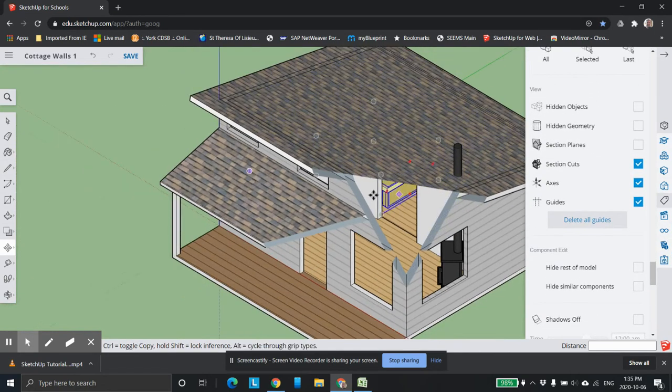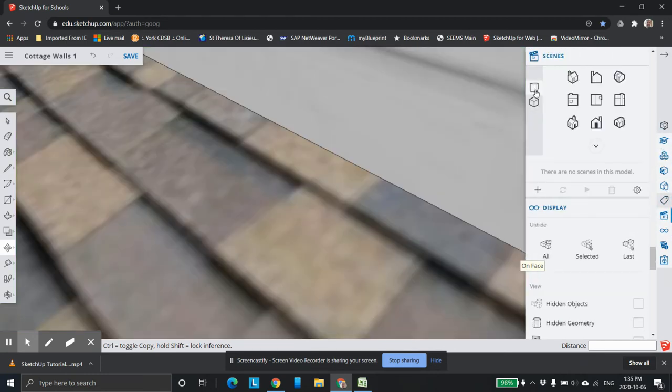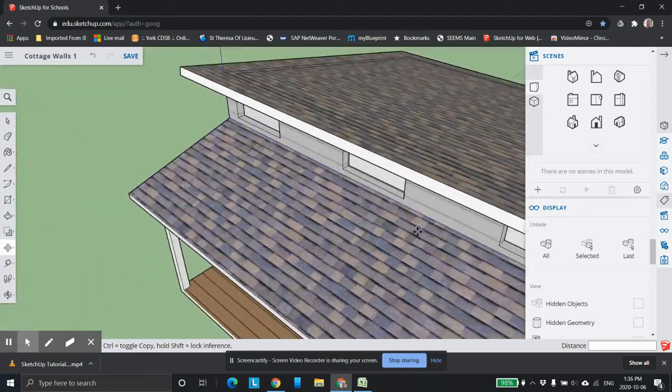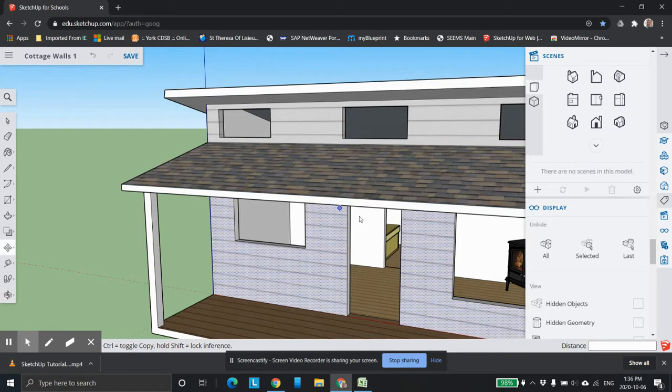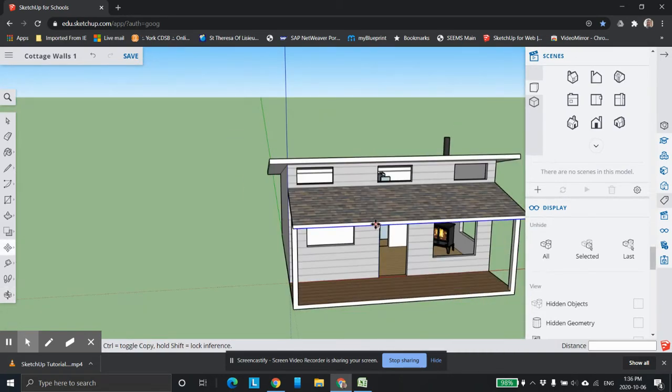Now, if you look here, you'll see clipping. I think we've gone over this before, but it's okay, I'll do it again. What you do to get rid of that clipping is turn the perspective mode back on. And now if you scroll out, you can look around, and you can look right in the windows and see everything. You can see our fireplace there and so on.